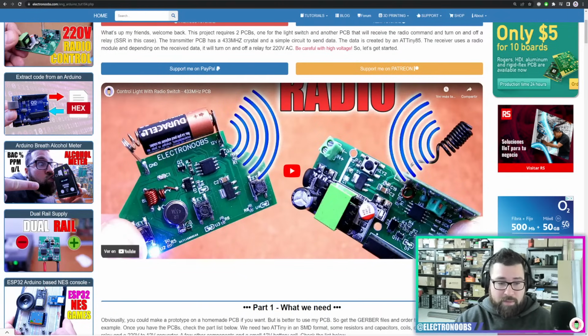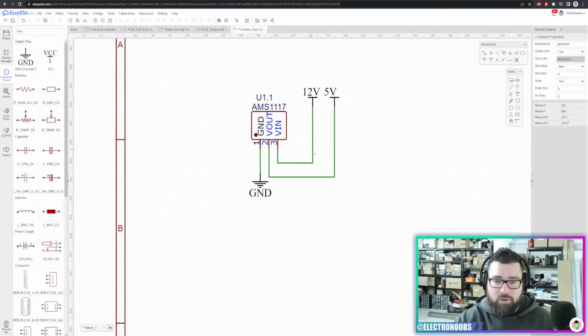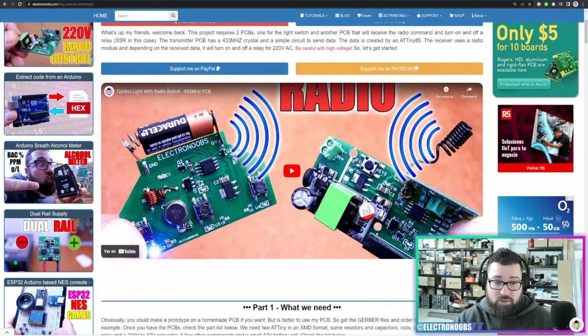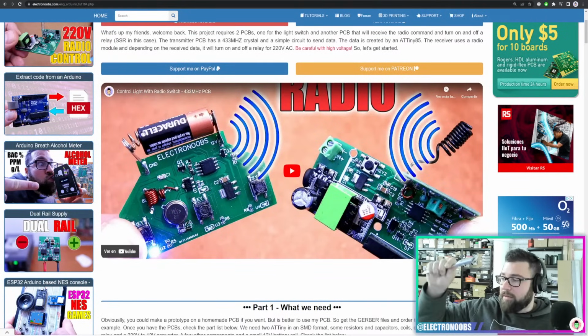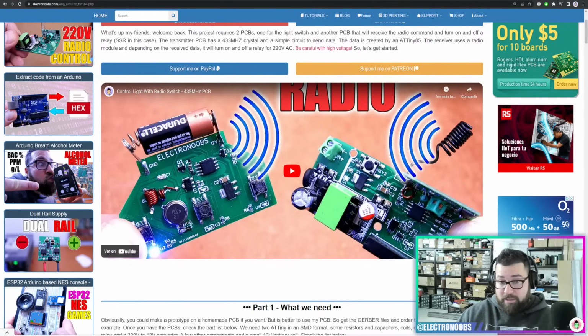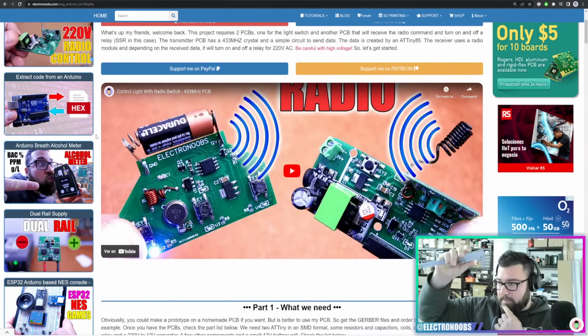Or for example, maybe this coil is a coil that you wind yourself, so you won't have a stock symbol or PCB layout for your PCB. So instead of doing that, you just place 2 pads like this one, and then you measure it with your caliper and place that distance on your design. So have in mind that having a caliper with you is very useful.